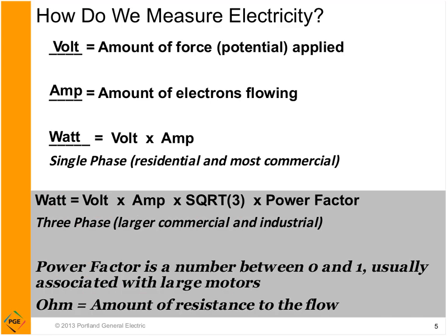For us today, we're going to assume the power factor is always 1, perfect, and anything times 1 is itself. But larger industrial and a lot of equipment would have 0.8, 0.7, something less than 1, and that significantly affects the amount of power that your facility needs.